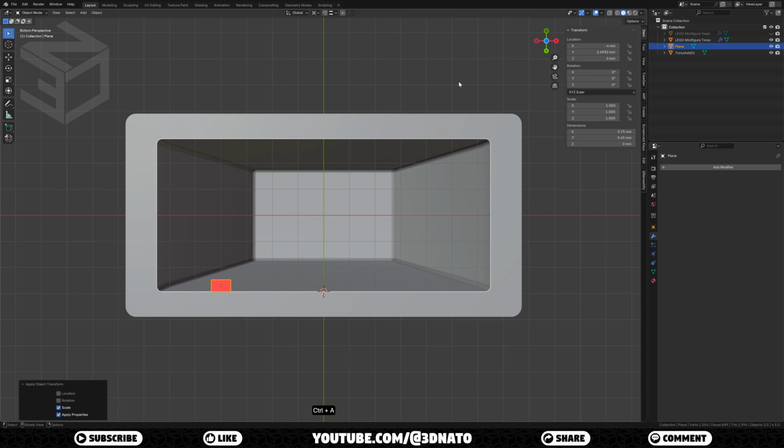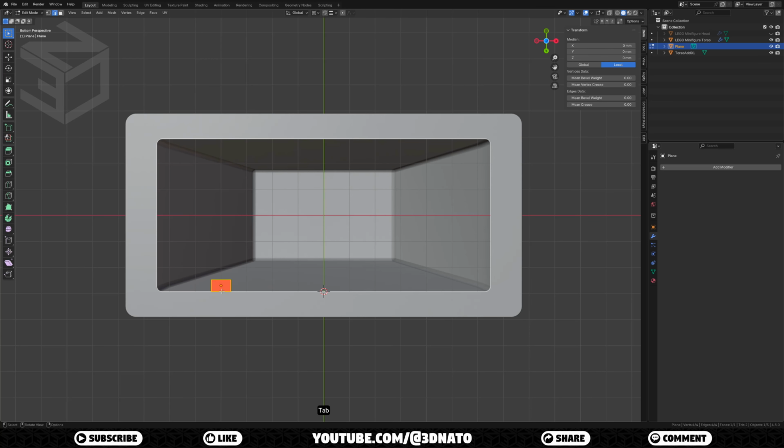To make sure the Boolean will work properly, let's move this bottom edge a bit inside the torso mesh. Go to Edit Mode, select this bottom edge, press G to grab, Y to lock the axis, type 0.1 and enter to confirm. Press Tab to exit Edit Mode.